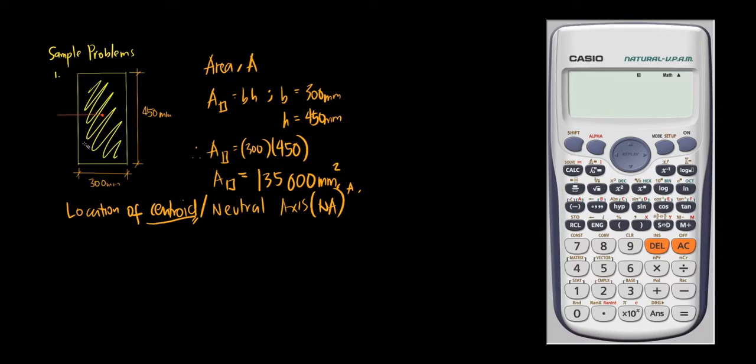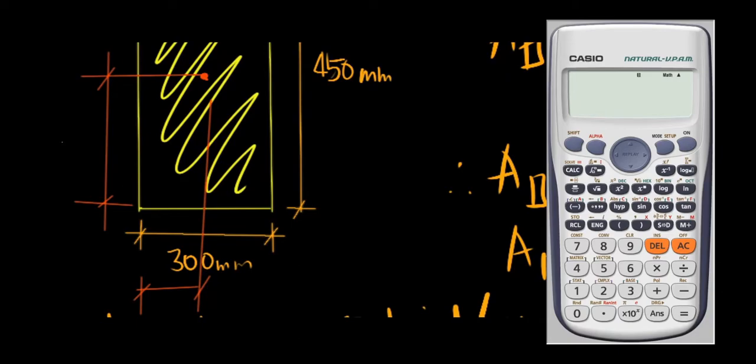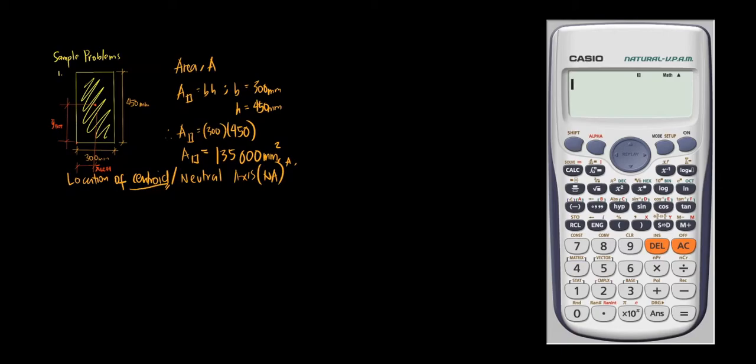So you have distances along the y-axis, or the vertical axis, relative to the section. We also have measurements from the x-axis. Our reference point is the lower left point of our steel section. Our annotation right here will be y bar bottom, which denotes that our measurement is from the bottom part of our section, parallel to y. The other measurement is from the leftmost part of our steel section, parallel to the x-axis, horizontal.